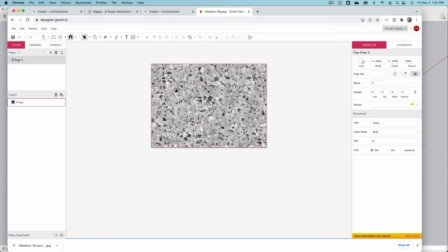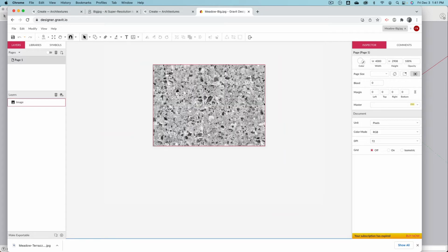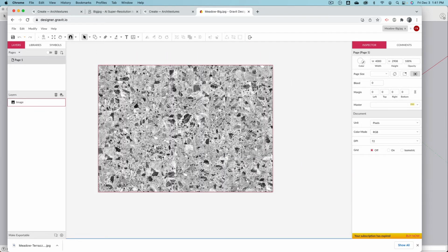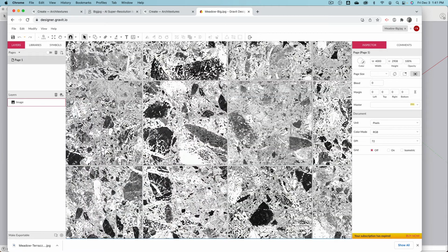The mouse wheel is zoom in and zoom out, and the middle mouse button pans around. Tools, don't freak out. We're doing just some lines, layers, and then here are some properties, and then export. When I zoom in, there is also a zoom tool here.